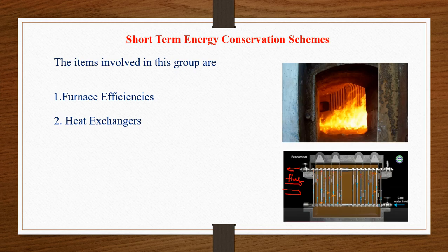So then the boiler takes less heat energy to boil the water. So that is what a heat exchanger is. And this also you have to maintain properly. The careful monitoring of the performance should be carried out. In all these short-term energy conservation schemes, the main thing is monitoring and cleaning. These two are the important things, because for these two, there is no need of any investment, and we can get some savings from this.